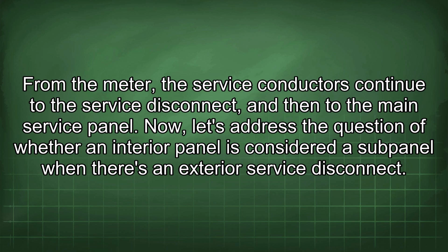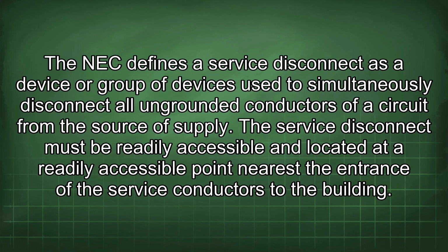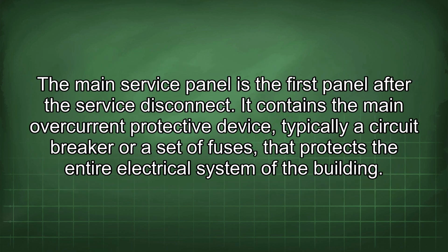Now let's address the question of whether an interior panel is considered a subpanel when there is an exterior service disconnect. The NEC defines a service disconnect as a device or group of devices used to simultaneously disconnect all ungrounded conductors of a circuit from the source of supply. The service disconnect must be readily accessible and located at a readily accessible point nearest the entrance of the service conductors to the building. The main service panel is the first panel after the service disconnect.